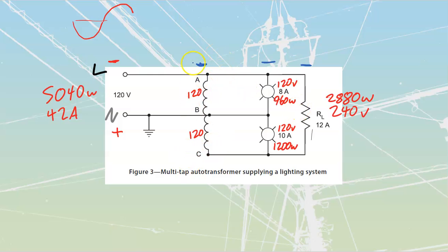These ones over here get a little bit tricky because one has to be a source, one has to be a load. We understand that, we know that, we'll assess that after, but these are all loads, which means that all of these, the current is going to have to travel in and down for each one of these. So if I take a look at this node over here, I know that coming out of that node, I must have 12 amps. I'm going to erase that one there and those lines over there. We're going to say we got 12 amps coming out over there.